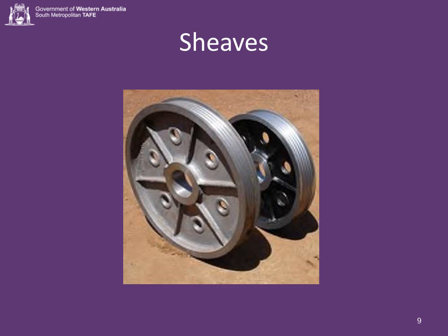Sheaves are made of cast steel for heavy-duty applications. For lighter applications, they are forged out of steel plate. Cast iron sheaves are always used in applications where fluctuating loads are present. They provide a flywheel effect that minimizes the effect of fluctuating loads. When they are mounted to a shaft, sheaves should be straight and have little or no wobble.